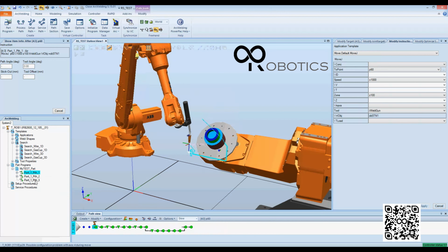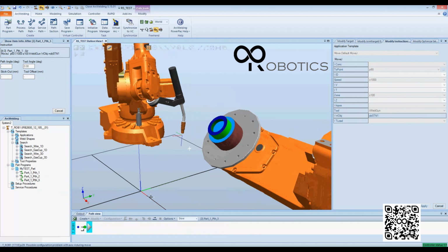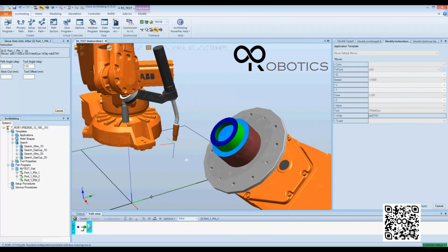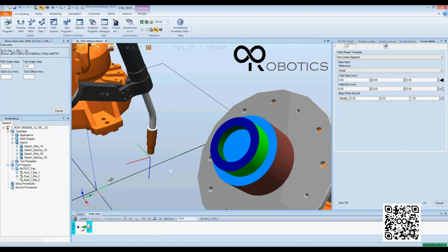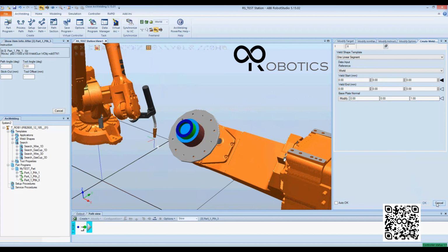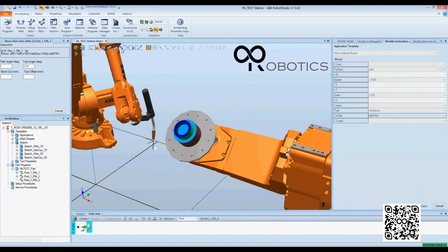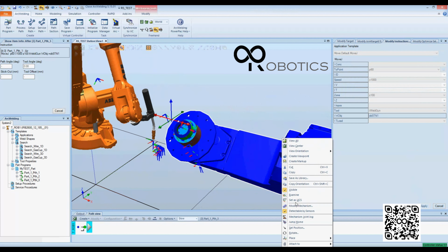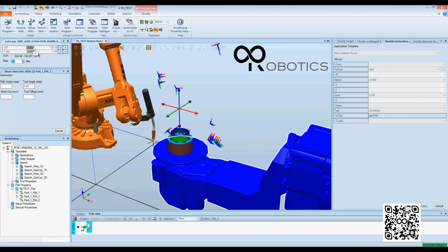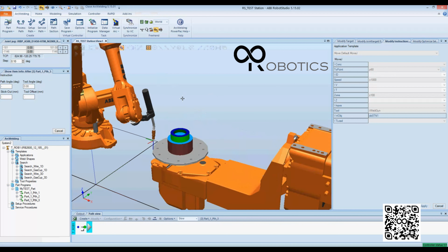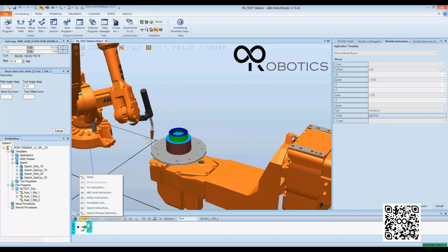create process path. So I'm going to create a new path along this target here, create weld. So first I'll put the positioner into a flat position and then try to update things and rotate things around. So I'm going to go right here, mechanism joint jog 0, 0, and then I'm going to create a weld on this,